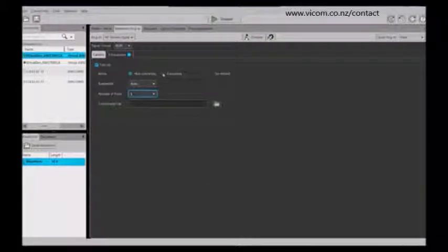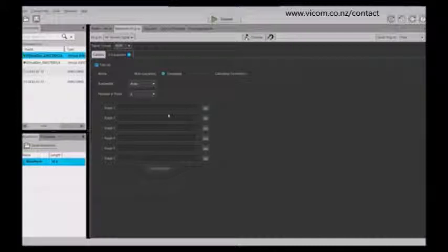Now we also have the ability to cascade S parameters, so that if you have more than one component, you can add all the components that you want to use. These S parameters have to be of the same port number, but you can add plenty of them to your system, so if you have several filters or several other components in your system, you can add them as an S parameter.